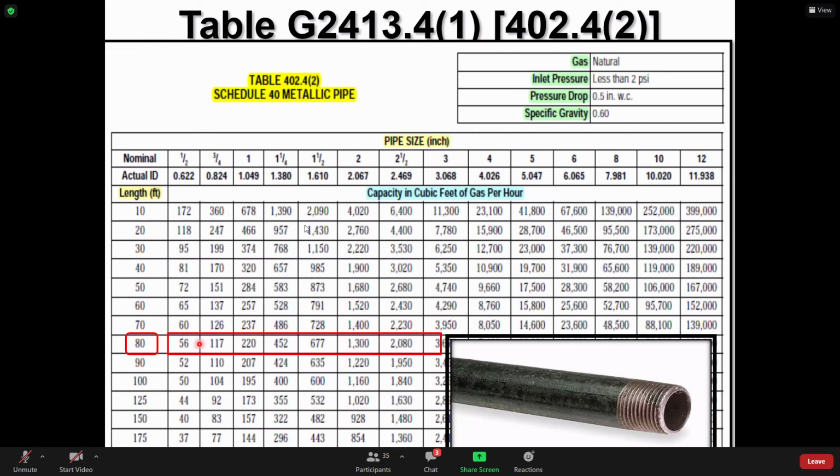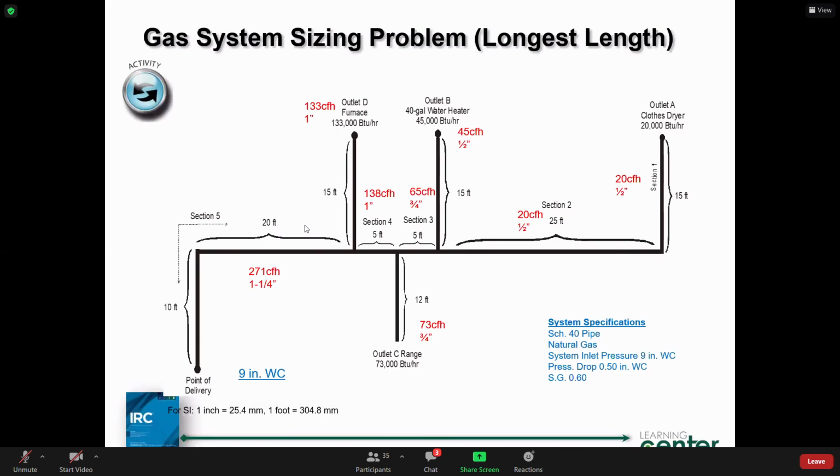I say, yes, it is. I use that first value, go all the way up to the top and size those two sections at half-inch pipe. Half-inch pipe. So I go back, checking the size. Maybe I'm a plans examiner, right? I check this and I say, yep, so far so good. Based on these parameters in that table, that's half-inch, that's half-inch.